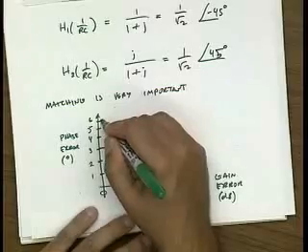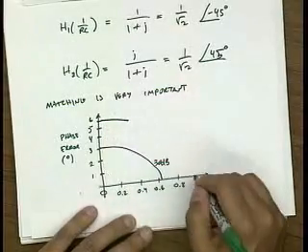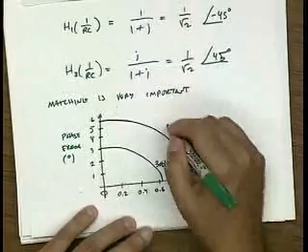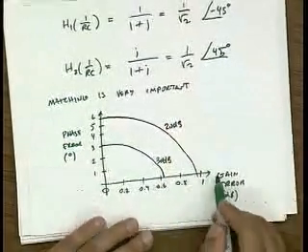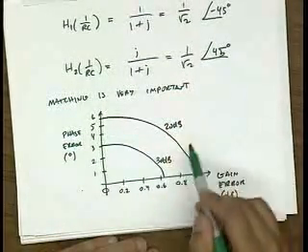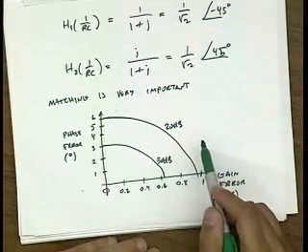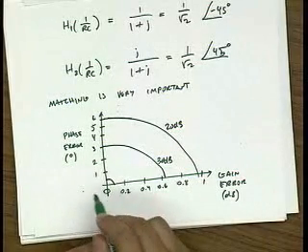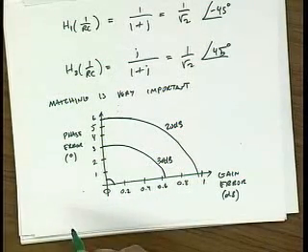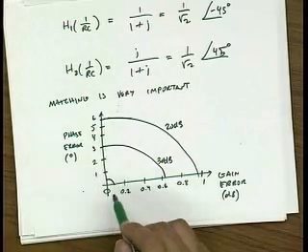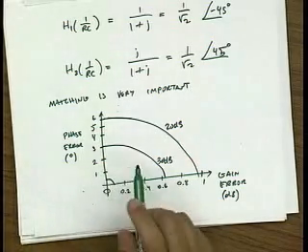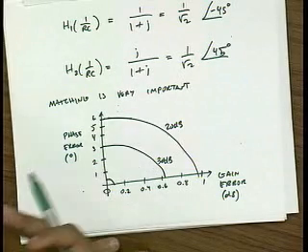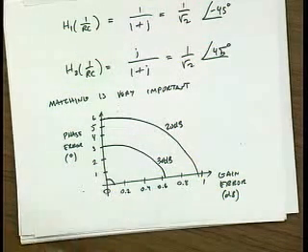Of course, as you go out more and more, somewhere out here, this would be a 20 dB image rejection. The more gain error and phase error you have, of course, the less image rejection that you have. And if you want a lot of image rejection, you have to be over here, which requires very, very precise components. Now in real life, you'll never get that much precision. So the only way to get to, let's say, more than 40 dB of image rejection is some kind of calibration scheme. You need to actually tune your components to get that much image rejection. Okay, questions?